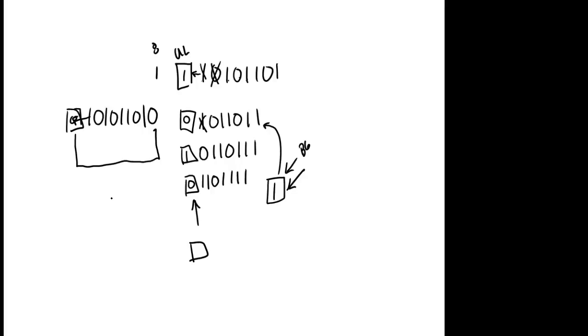Strobe: load it with all ones and shift a 0 through, or load it with all zeros and shift a 1 through. Or I can make it go all the way to the top, and then bring it back, going on both sides. You can make some awesome Christmas displays. You make it go this way for a little while, then you use timers to make the shift go back the other way.